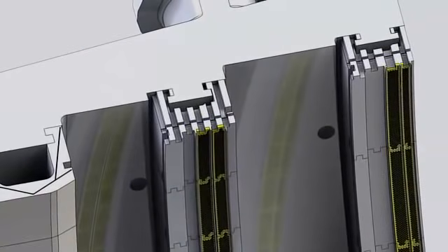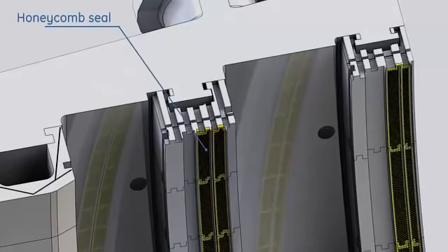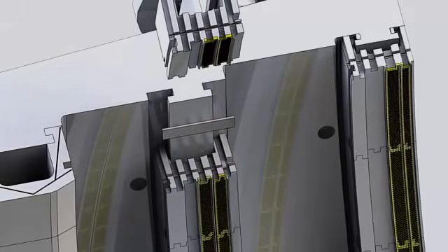The second and third stage shrouds have teeth that mate with teeth on the tip of the second and third stage buckets. This labyrinth seal minimizes tip leakage. For better tip clearance, a honeycomb seal is integrated on the second and third stage shrouds. This honeycomb is relatively soft material. The cutter teeth on the tip of the second and the third stage buckets open a slot on the honeycomb seal without any material transferred, providing tighter clearances to improve the unit efficiency. Shrouds of the last 2 stages are sealed by interconnecting tongues and grooves